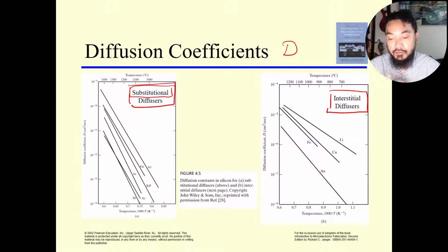Therefore, you can contribute extra electrons or holes, and it is slower and easier to control. Whereas in interstitial diffusion, the impurity atoms reside in the interstitial location, with no covalent bonding and no sharing of electrons or holes. At the same time, the diffusion is very fast and hard to control. It's very hard to control the dosage, the shape, or the profile of your diffusion.